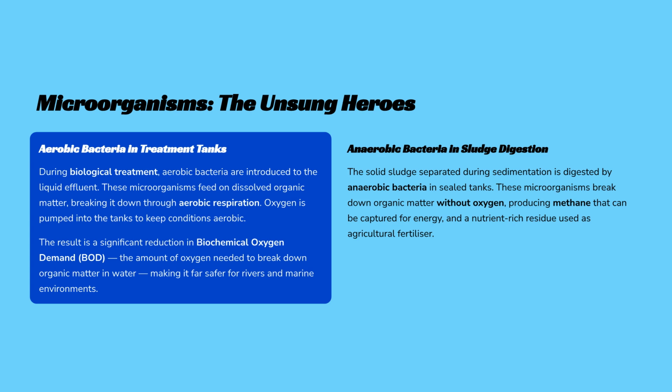Microorganisms are the unsung heroes of this process. Aerobic bacteria in treatment tanks break down organic matter to reduce biochemical oxygen demand, while anaerobic bacteria in sealed tanks digest sludge, producing methane for energy.